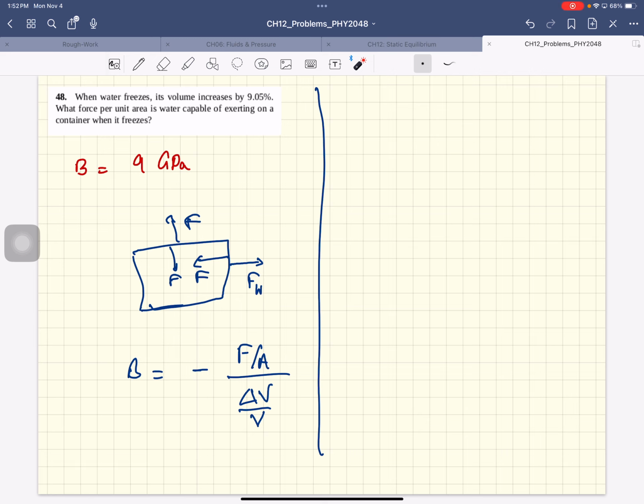How much did the top surface of the disc move relative to the bottom surface? They want you to find that shear deformation. Okay, or since we have h, we can calculate that. Okay, so delta x over h is force over area. We can calculate delta x.